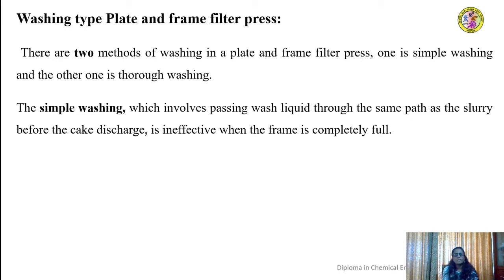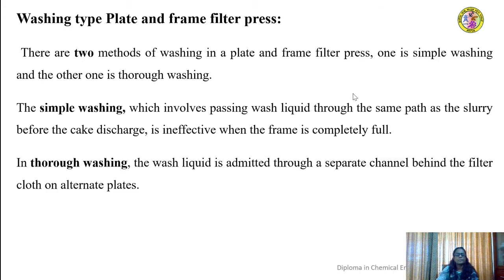That is, whenever the cake that is formed will not have much of the porosity, then the filtrate will not that easily pass through the entire cake bed thickness, in that the washing cannot take place fully. So that is the inefficient washing, what is happening in a simple washing.